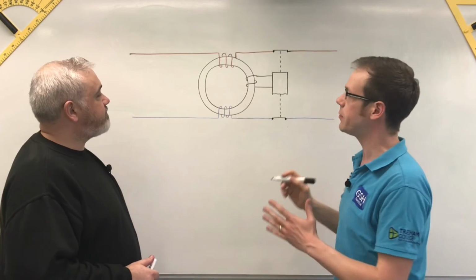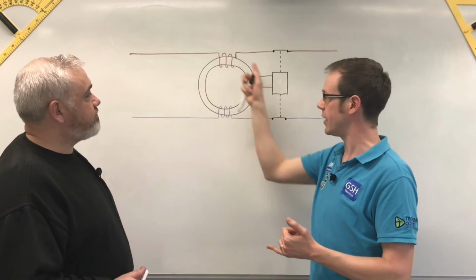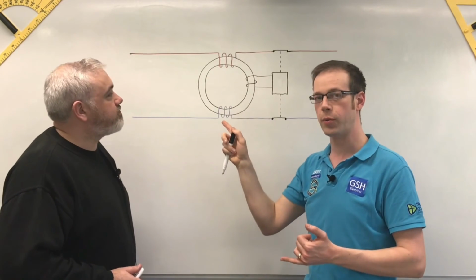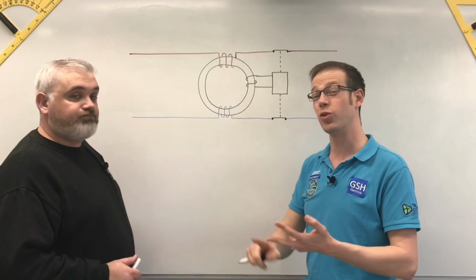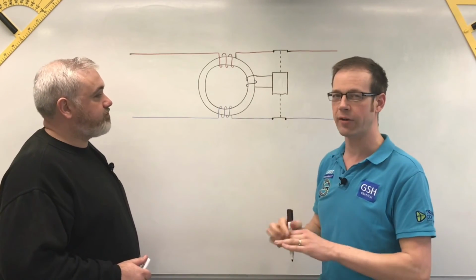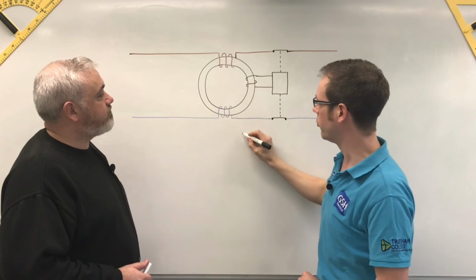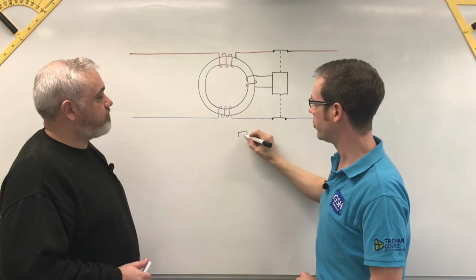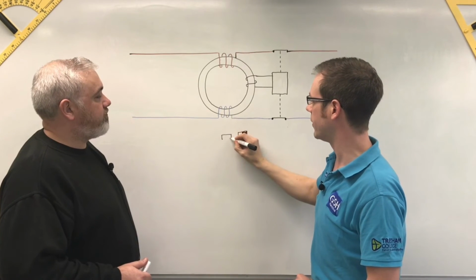Yeah. Now the reason this becomes a problem is it has an effect on the iron core. This is actually the bit that causes us the problem, because the iron core can become shocked, stunned or saturated by that higher current in the positive direction. Now the reason that happens is that inside this iron core, the little molecules of iron are all shaped like little tiny bar magnets. So they all sort of look a bit like this.